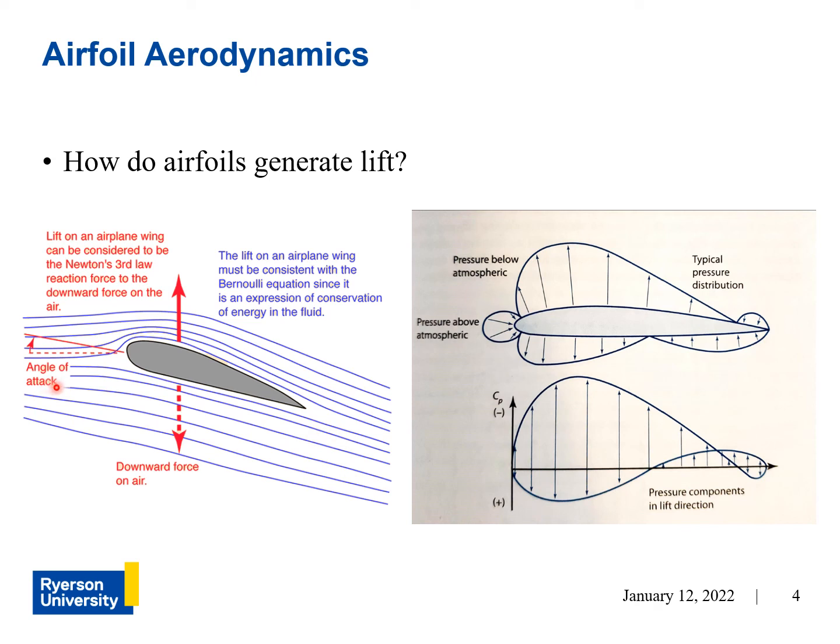And the angle of attack, which is usually denoted by the Greek letter alpha, refers to the angle of the airfoil's chord line with respect to the flight path. Now the airfoil's chord line is just the distance between the leading edge and the trailing edge, and the flight path is just the direction of the flow of air upstream from the airfoil.